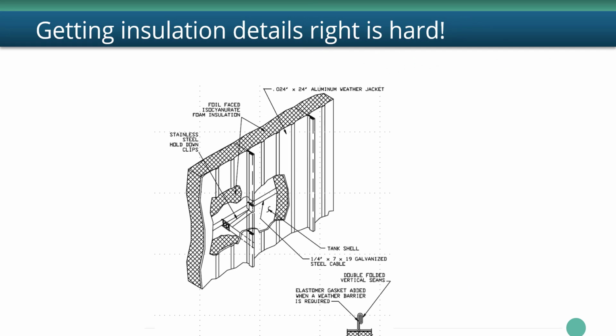Tanks are big, so these insulation systems have to have straps for thermal expansion. The insulation has to be able to move with the tank. It's a fairly complex system. So if you're going to insulate, you should be studying these systems. Some are better than the others, and they are all somewhat complicated, and every one of them, it's very difficult to keep all the water out.